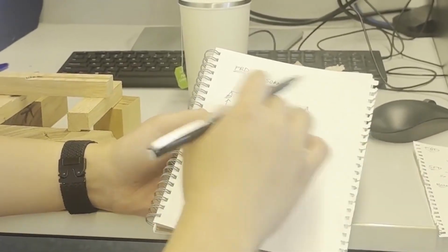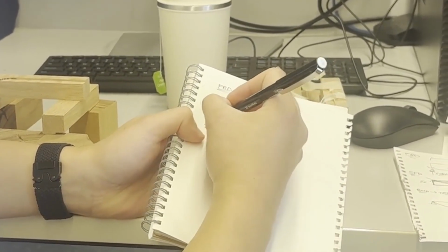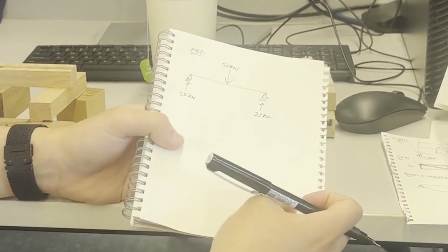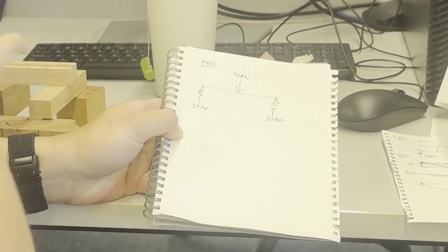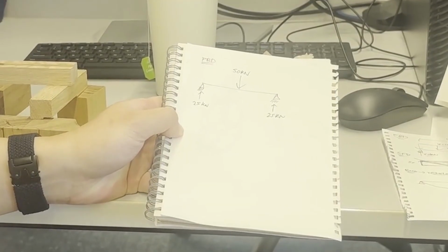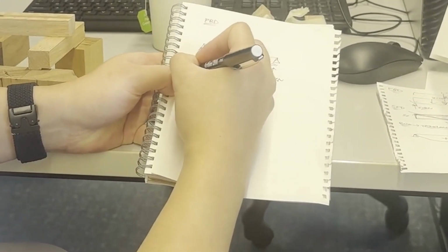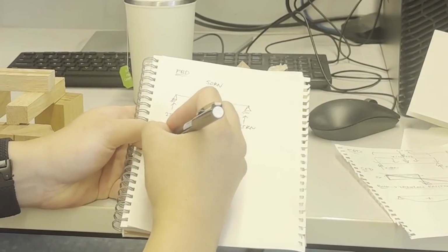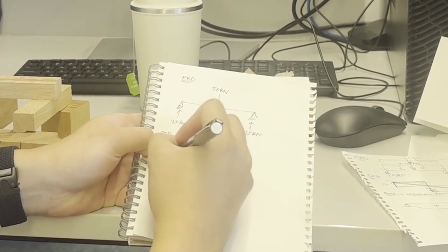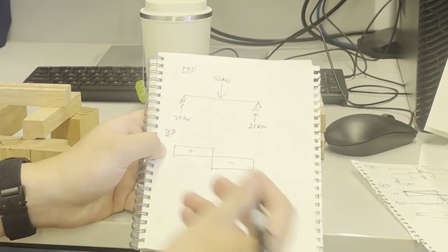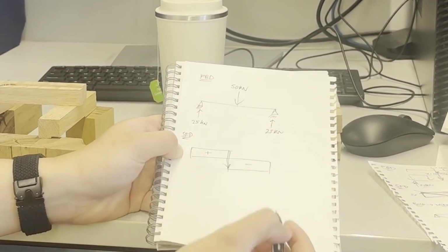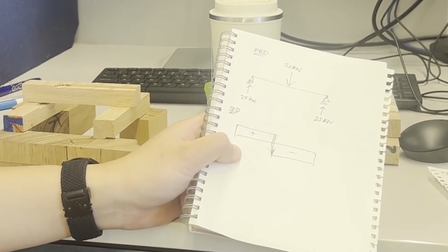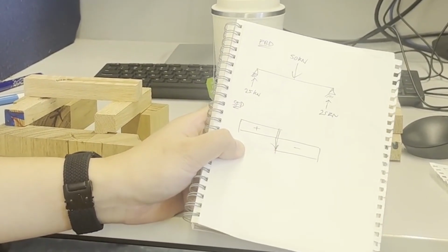So yeah, now you've got the reactions again, 25 and 25, because we've got two primary beams supporting your secondary beam. And they're kind of splitting the load, if that makes sense. In terms of your shear force diagram, now instead of two triangles due to that slope, you've got what I drew before. You've got this sharp jump in shear, and I'll explain that more in the shear topic, which is week 7, okay? But the idea behind shear and bending is this is vertical shear.